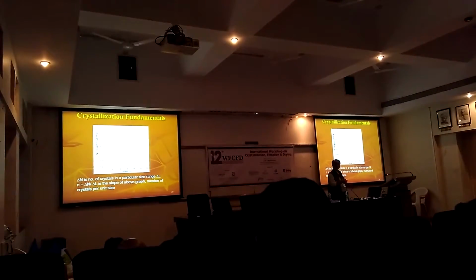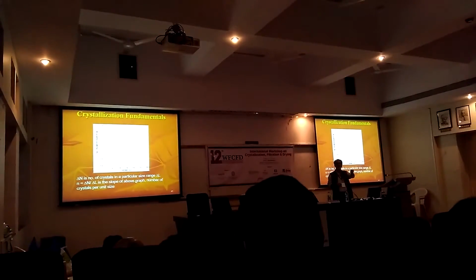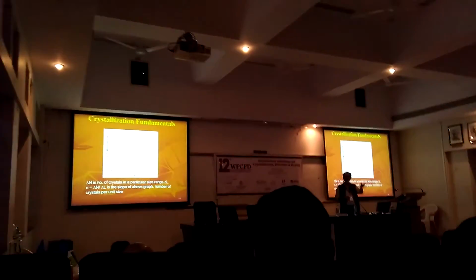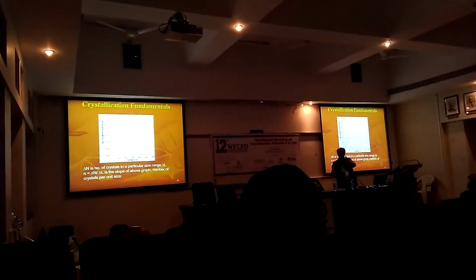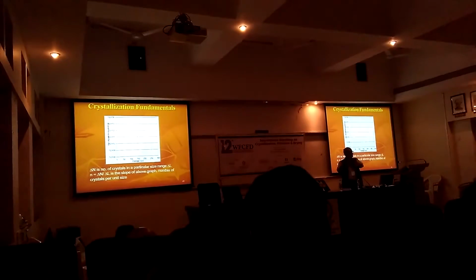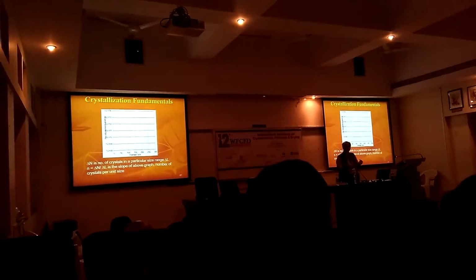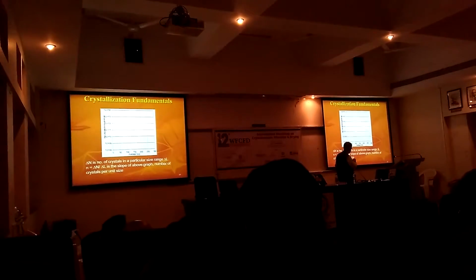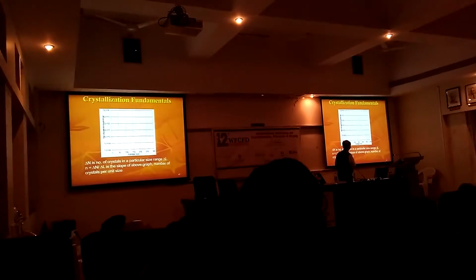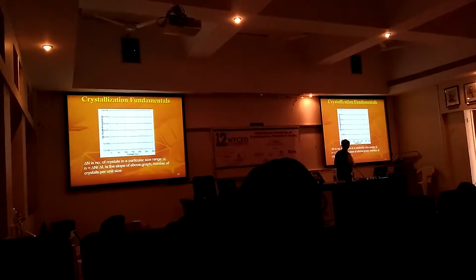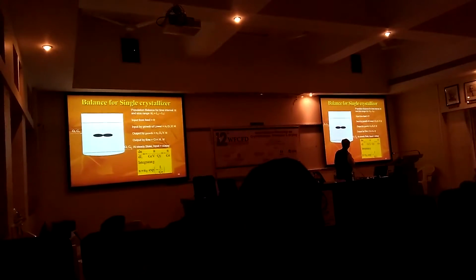Versus average size. Very similar to log scale versus temperature. I can have log scale versus size, and I can decide various bins. The slope of this is extremely useful, as I will show it to you in a minute. And this slope can be utilized to estimate the crystallization kinetics, nucleation as well as growth.